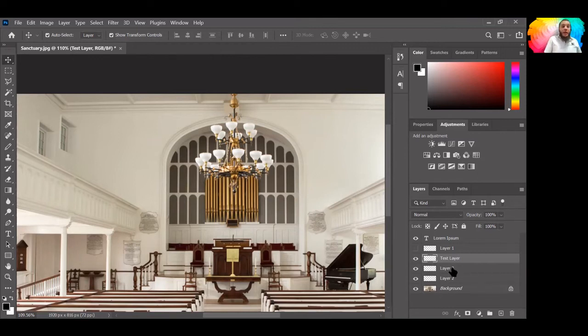You can easily rename a layer. All you need to do is double click the layer name. Let's see. I think that's the window. Nope, layer 2 is the window. Okay, so I'm gonna rename that to window, and all you need to do is double click the layer name directly. Orderly naming helps keep you sane because you can quickly accumulate dozens and dozens of layers in Photoshop.